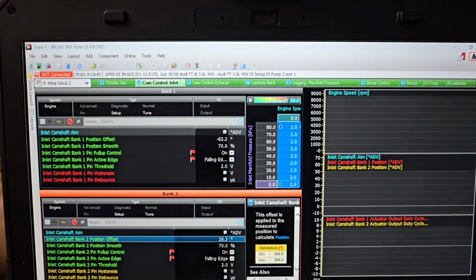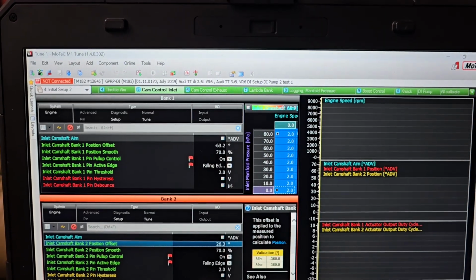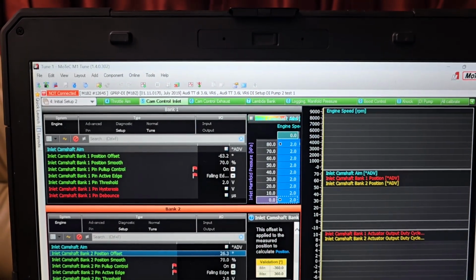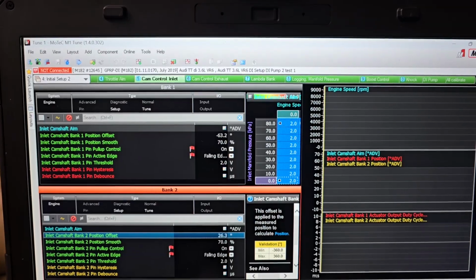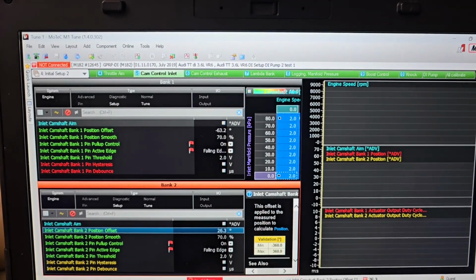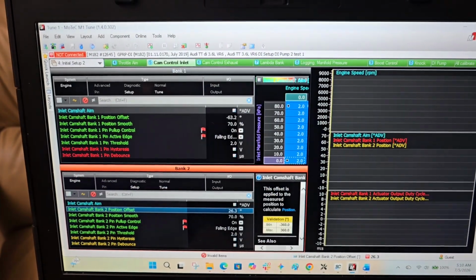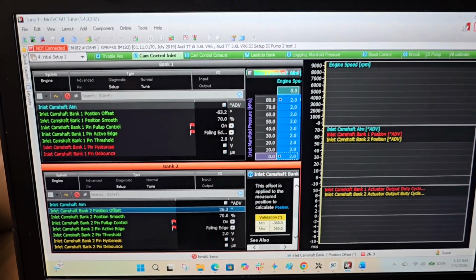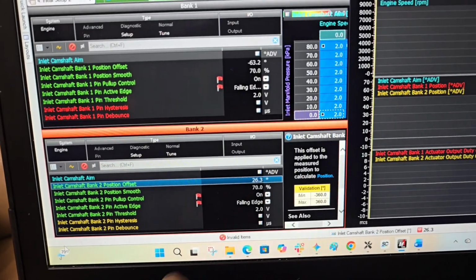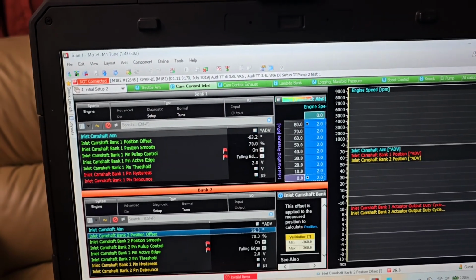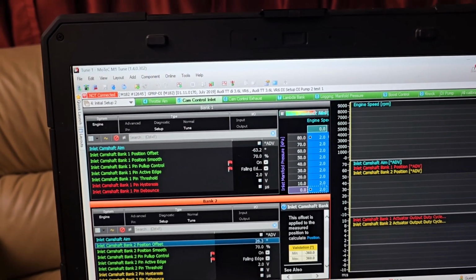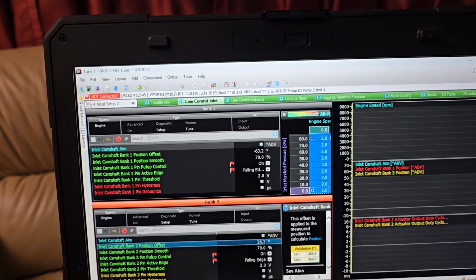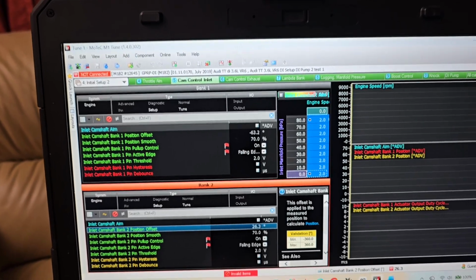I'm currently working in an offline mode on the Motec and continually consolidating the software to match my physical hardware for the Audi TT 3.6 liter engine. I need to disable the Bank 2 camshaft output resources, and what this will do is reduce any invalid errors that I currently have on the computer, as well as free up any extra pin output resources that I can use for other important sensors.